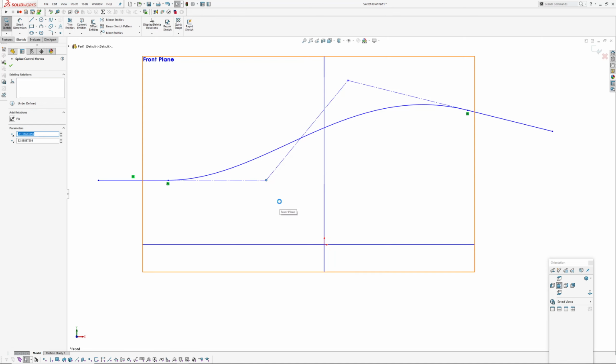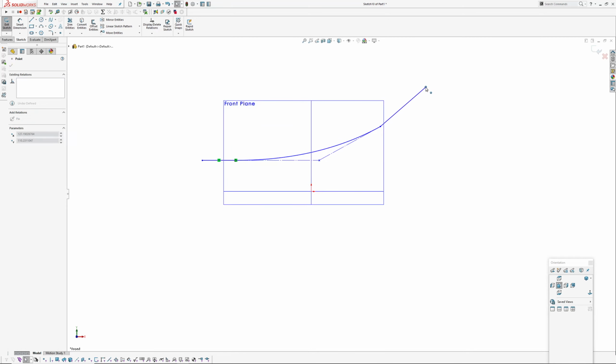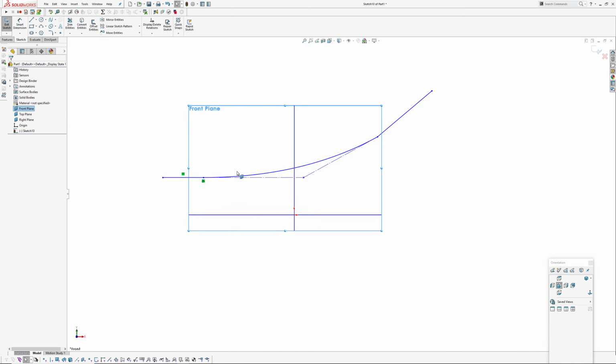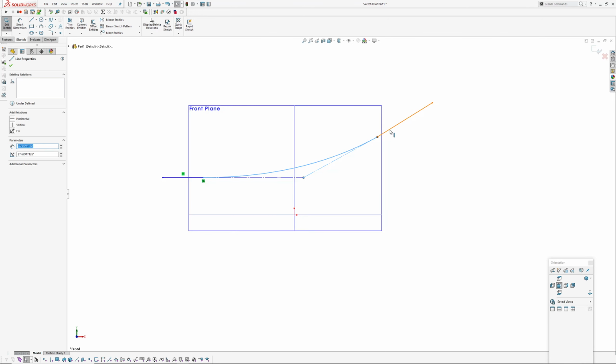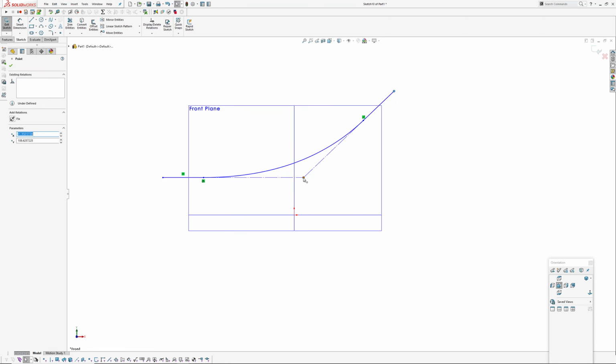Now if I want, I can delete one of those points. You can have a tangent connection on each end with only a degree 2 curve, but there's no inflection in a degree 2 curve, so the curvature is all one direction. It's like so. Okay, but now there's only one control point in the middle, and each end depends on the other.